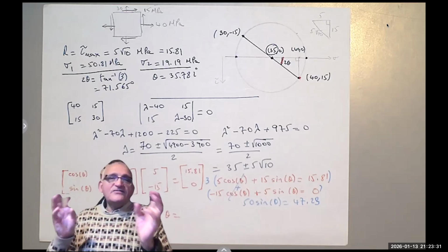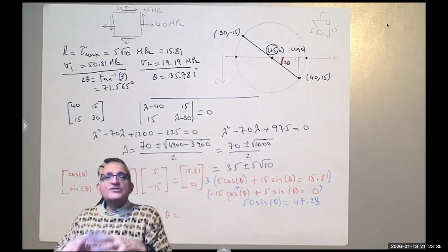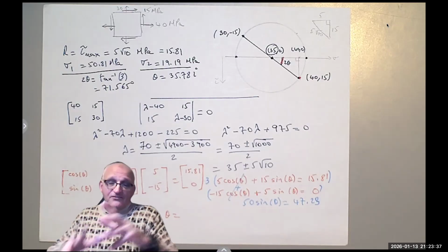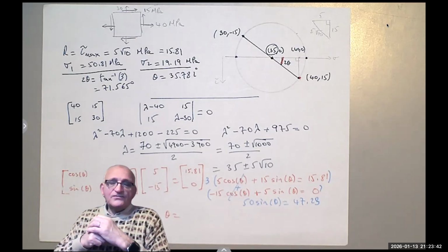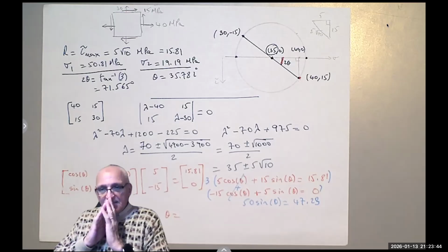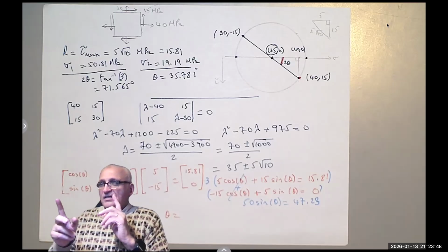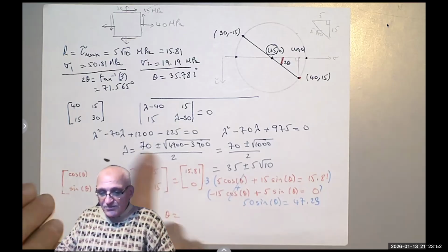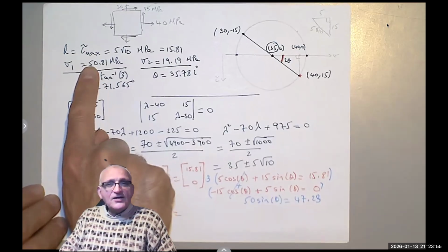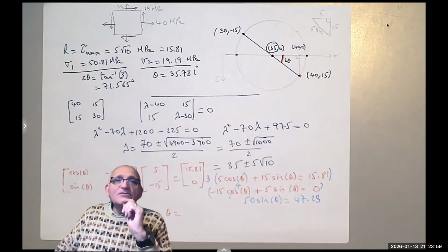When one is positive and the other is negative, the maximum shear occurs in the XY plane, like 45 degrees from the principal axis. But if they are both the same sign, then the maximum shear will not be R that you see here, where we said tau max. It's tau max in the XY plane, but it's not the maximum shear that the element is subject to.